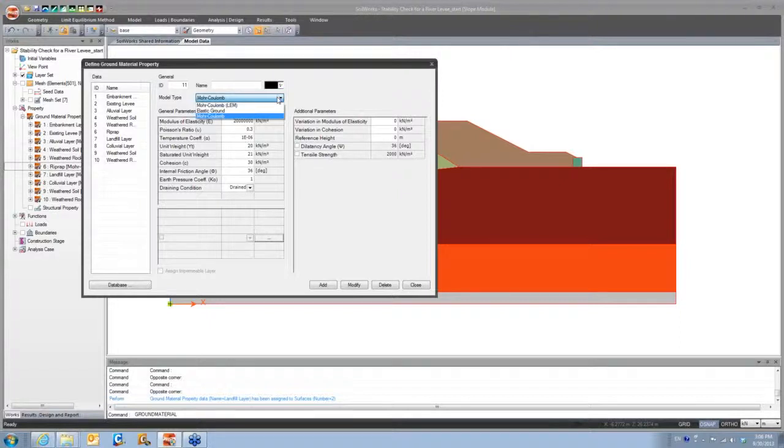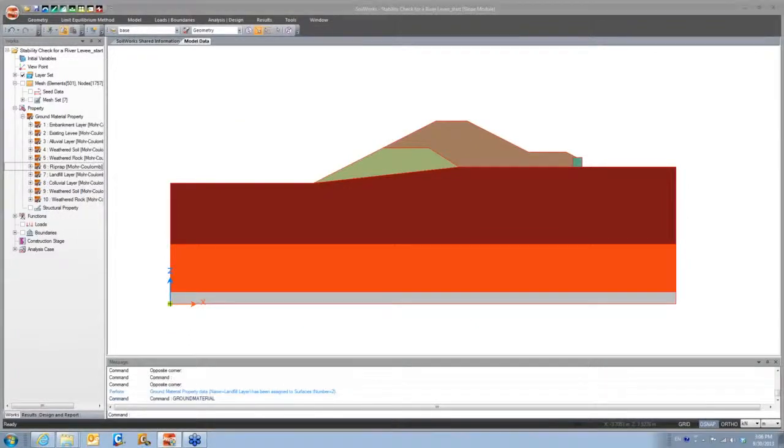But since this is a slope stability module, Mohr-Coulomb LEM is typically the most common one used, so it's included there. Very true. Yeah, I saw it. You could probably use a hyperbolic model or something, and there are many different options. What I'll do is, after I run the slope stability analysis, I'll show you in the ground module all the different constitutive models available to you, because the ground module has the most constitutive models, since it's typically used for excavations, retaining walls, tunnels, things like that.